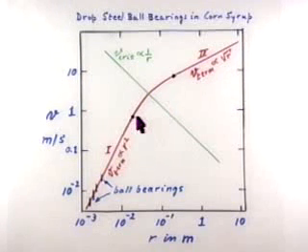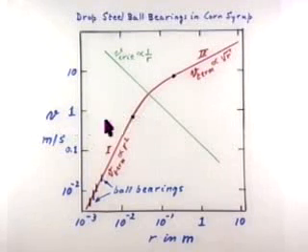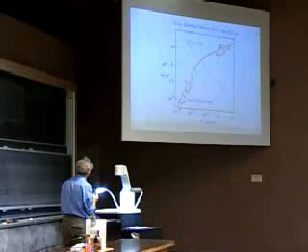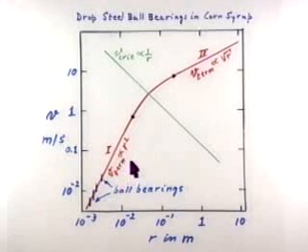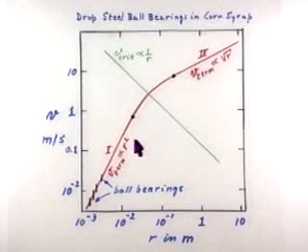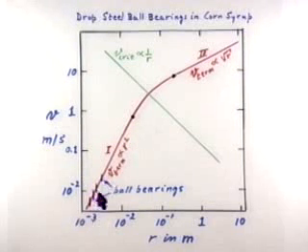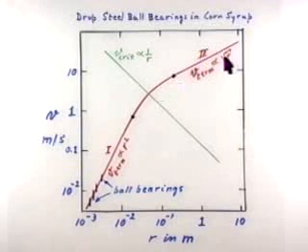This black dot is a factor of 10 below the critical speed. And so when you are at lower speeds, you fall exclusively into domain 1, and you see that the terminal speed is proportional to r squared. This slope here is +2 in this diagram, and this slope here is +1/2.